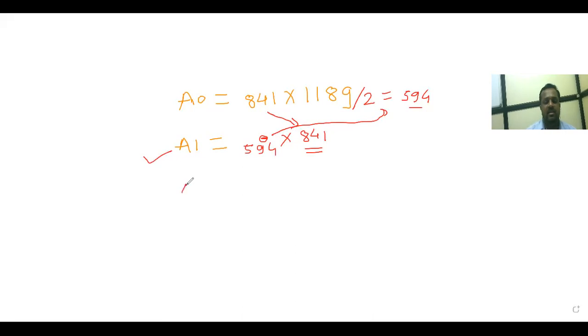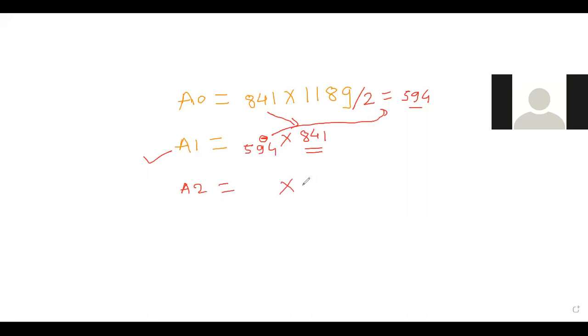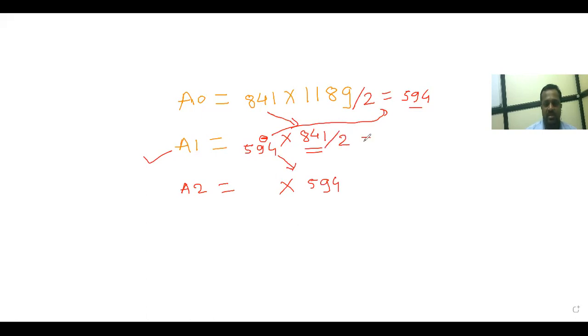Okay, then tell me the size for the A2 sheet. First of all, which figure do we have to write down here? 594. We write this figure as it is on the right side, that is 594, and this figure we have to divide by 2. What is the answer? 420. Okay, and this 420 we write down at the left side. Now this is the size for the A2 sheet.